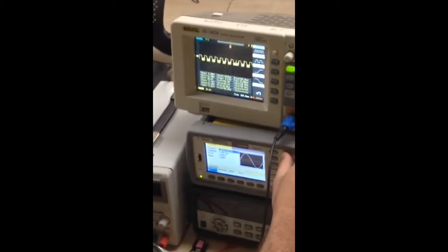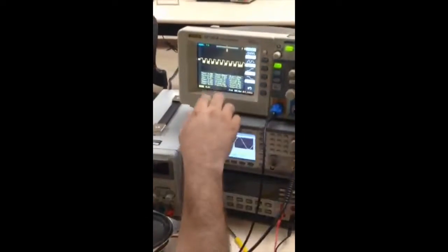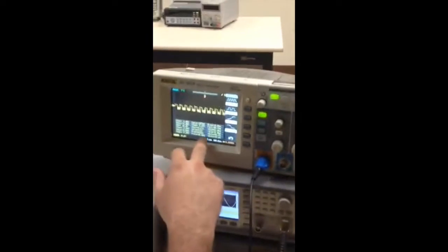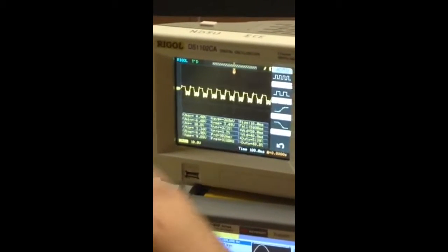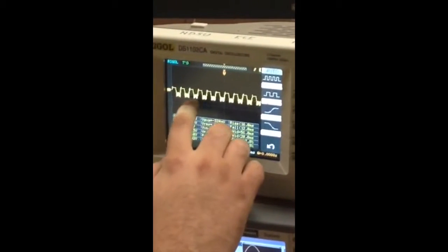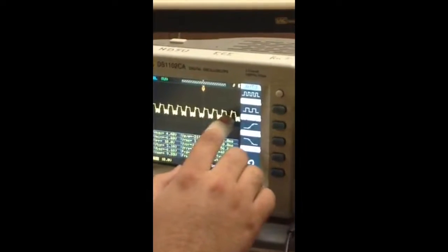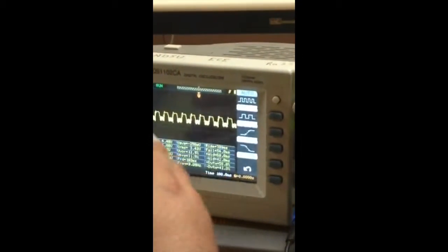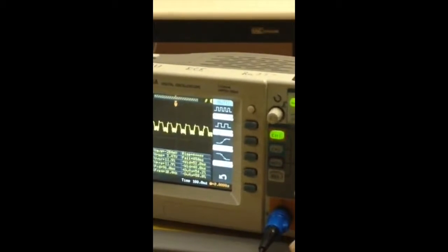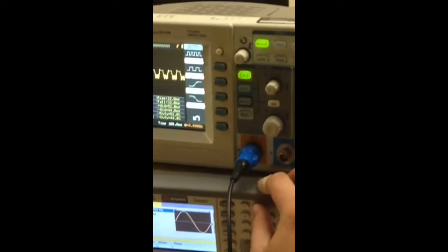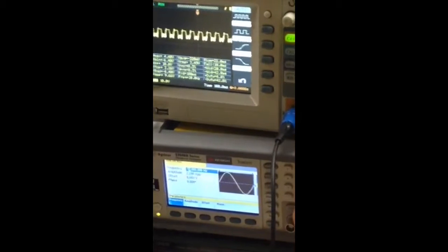Okay, now we're going to do the demonstration where we have set up the input signal to be 10 hertz. The amplitude is 2.2 volts peak to peak. So here we can see that the frequency in the oscilloscope is alternating between 8 hertz to maybe 15 hertz. That's because of the noise present in the signal, that you can see is not clear. There is noise in the signal. So we're going to increase the frequency to demonstrate how the signal is being filtered.